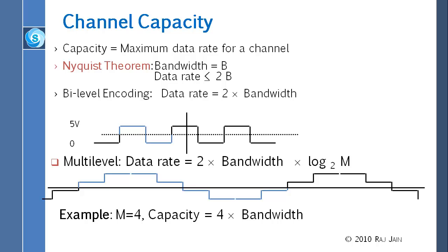If you want to get more than that, then you need more levels. And that's what we do in QAM. QAM is not two level. QAM has multiple levels. As we go more and more QAM, we have more and more levels. Right? So here's a multi-level signal you haven't seen so far. For example, in this signal, we have taken 2 bits and then made 4 amplitudes. So 0,0 is here, 0,1 is here, 1,0 is here, 1,1 is here.